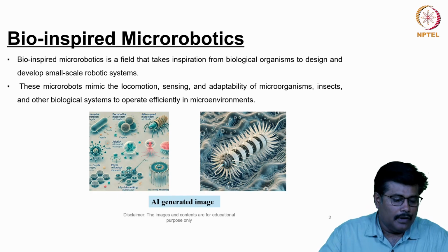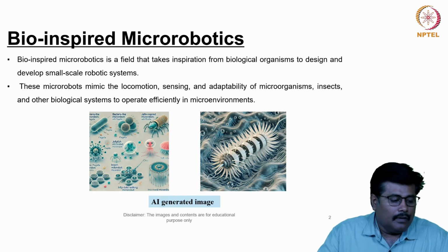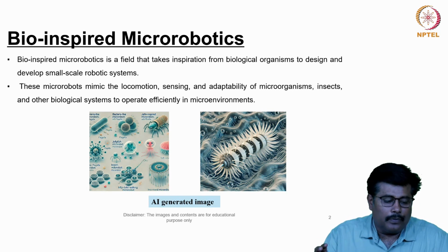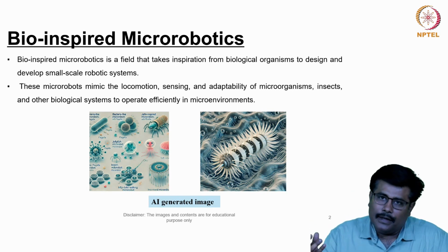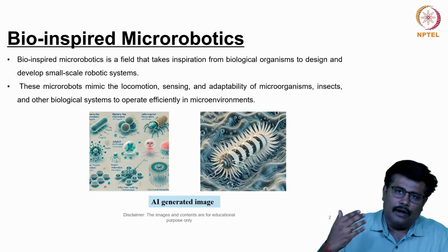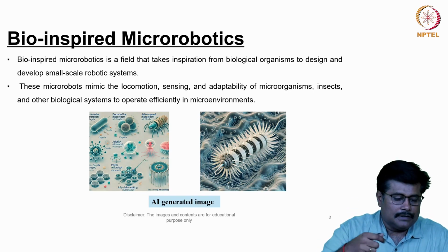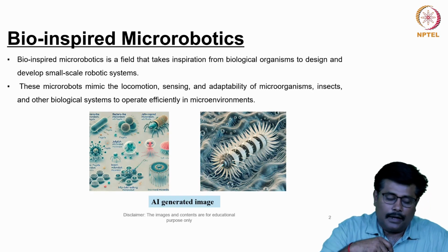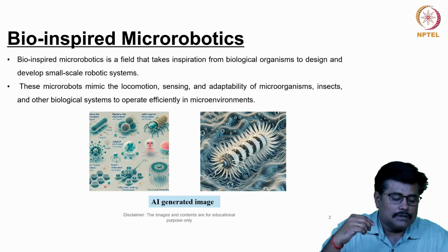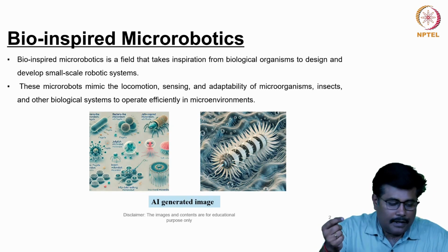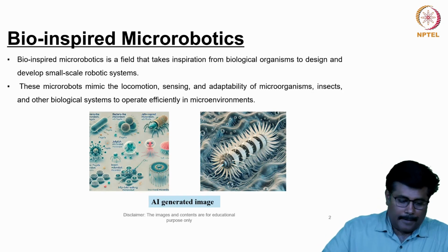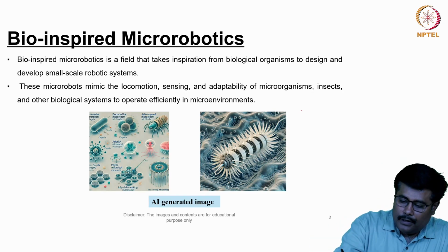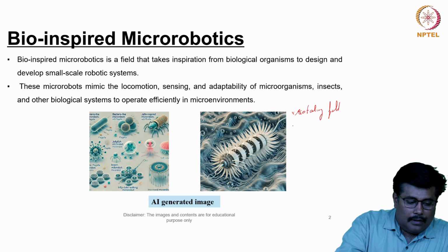We have also seen various types of locomotion that have been catered to the micro-robotic system, with the various swimming methods focusing particularly on helical propulsion, including the E. coli bacteria, a kind of bacteria whose propulsion characteristics we can mimic. There are various magnetic actuation methods for biomimetic and non-biomimetic micro robots. When we closely observe the mechanisms, we can classify them under the rotating field,